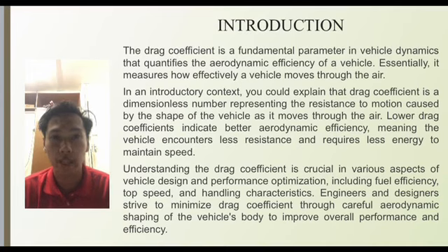In an introductory context, you could explain that the drag coefficient is a dimensionless number representing the resistance to motion caused by the shape of the vehicle as it moves through the air. A lower drag coefficient indicates better aerodynamic efficiency, meaning the vehicle encounters less resistance and requires less energy to maintain speed.